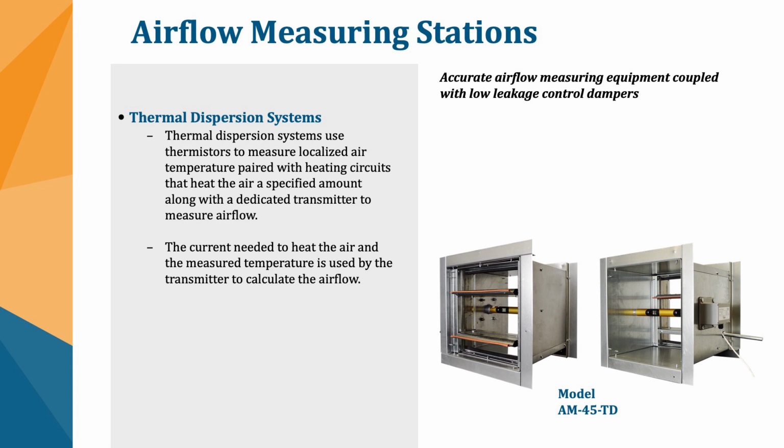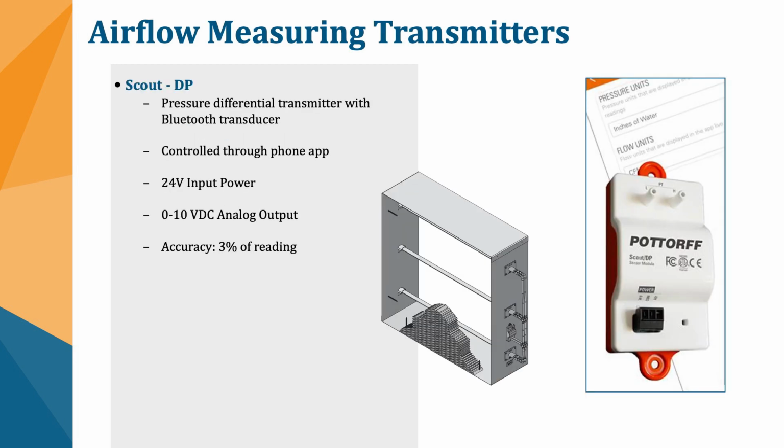You're probably talking a difference of 5 duct diameters without some type of settling device or extruded aluminum screen that helps get laminar flow upstream of the damper, where you only have to keep that damper within, say, 1 duct diameter downstream of the airflow measurement probes. So that does help quite a bit when you're laying out the overall system.